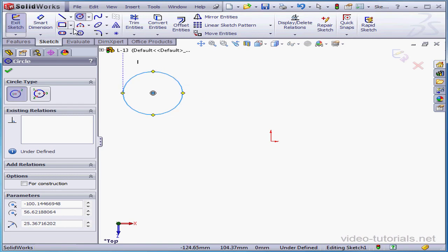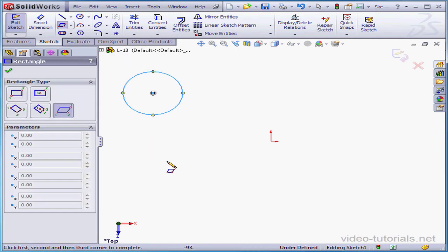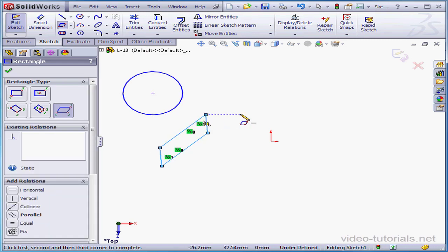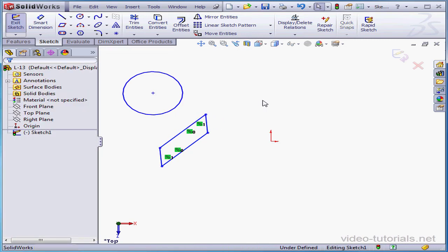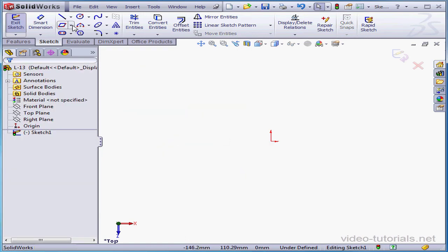Now let's activate the rectangle tool using the parallelogram method. I'll select my first point. Now the callouts display the current distance and angle of this potential segment, 55 millimeters at 45 degrees. Let's left-click to accept that position. Now the callouts display distance and angle for the segments that close the profile. And let's right-click and choose Select to close the tool. Windows Select and delete that geometry.